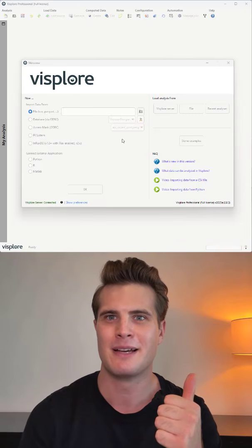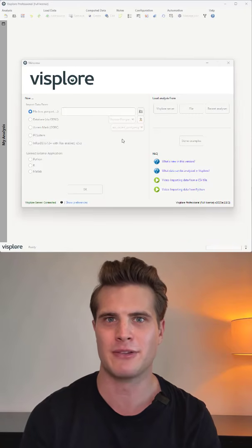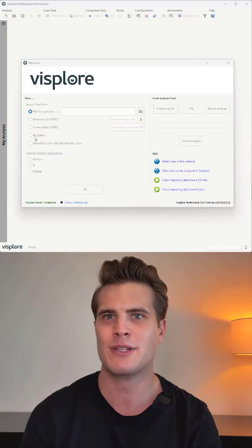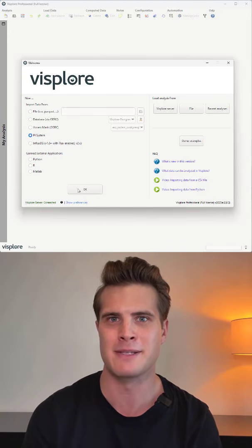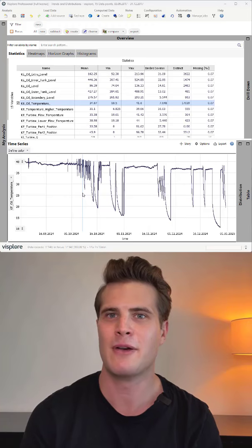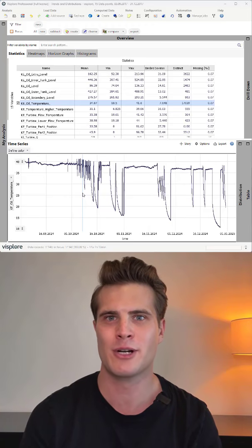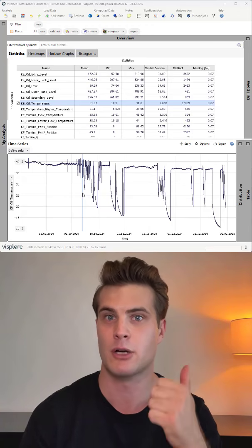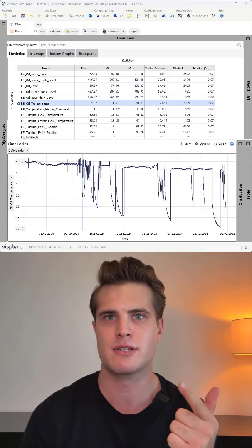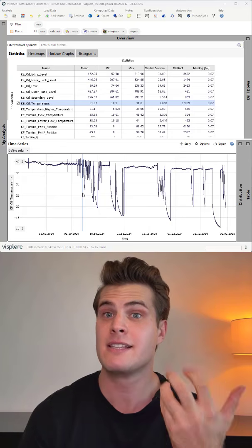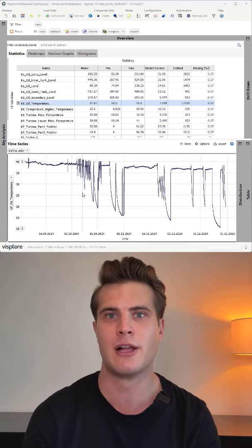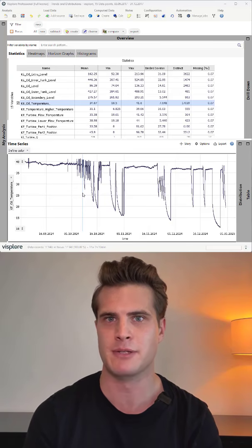The first step is getting the past operational data from the data source. So in this case, let's select the Aveva PI system. Now here we can observe the oil temperature over the imported time span across normal operations, interruptions, and shutdowns. And since we are only interested in monitoring the oil temperature during stable operating conditions, we filter steady state periods.